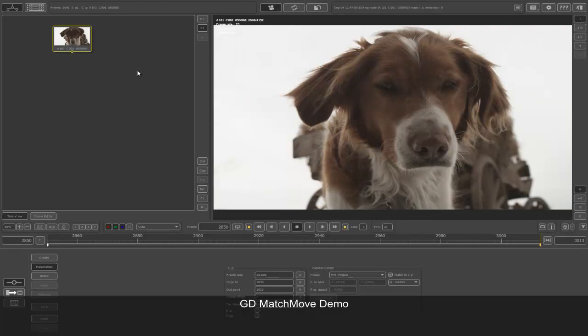So first off, right now this is already set to project. So if you had to set your own, all you have to do is for camera preset, go to custom, whatever film back values we have given you, just put those in, and then give the right pixel aspect ratio. For this project the entire way, this is the film back we'll be using. So over here it's 12.44 and over here 22.09, so that's constant throughout.